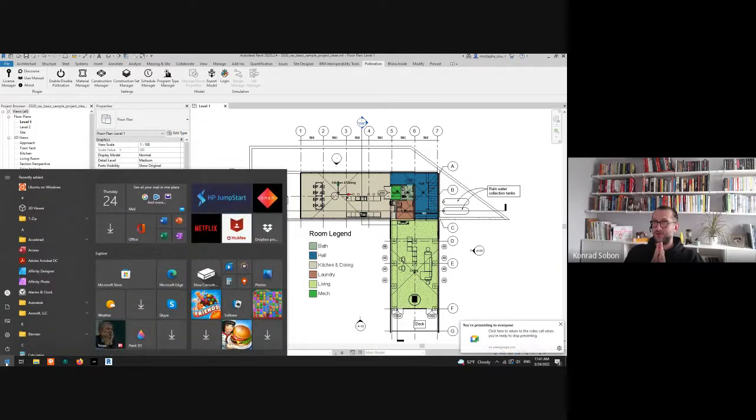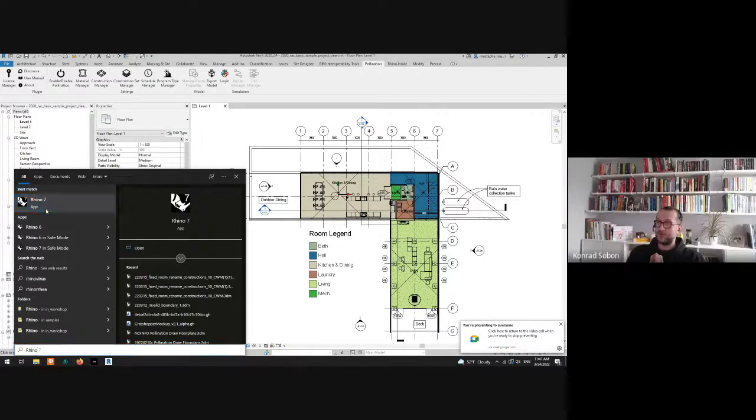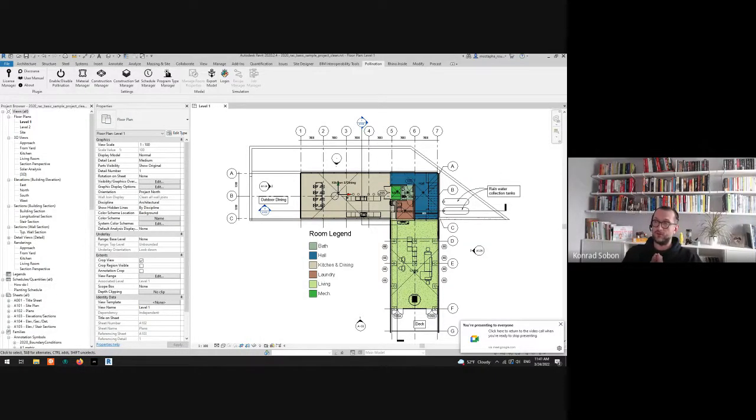Short of maybe in the future, we'll try to cure the model, so to speak, so that those surfaces become air boundaries. But for the most part, at the moment, there will be surfaces. There are a couple of instances where, for example, you have openings in walls and you draw a room separation line, because openings in Revit walls do not separate rooms. Your rooms would bleed through an opening in the wall, so people usually draw a room separation line through that. That is pretty good for generating air boundaries, because those usually come out clean for some reason. For all the other ones, especially when room separation lines intersect with walls, Revit does all sorts of weird stuff. So unfortunately, that will be a no in most cases.